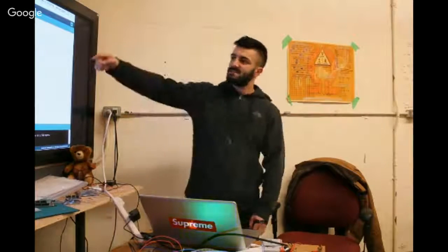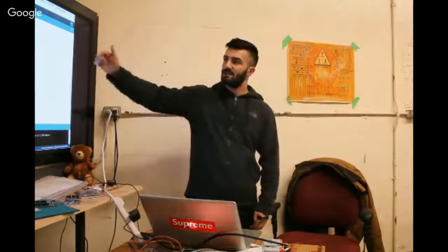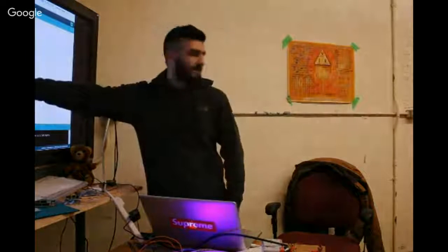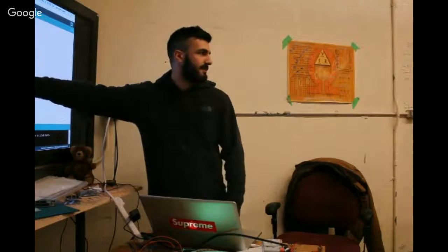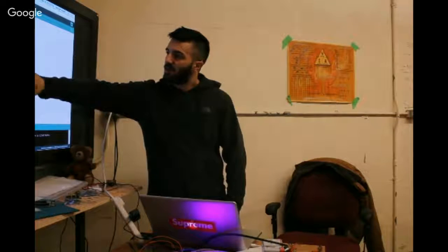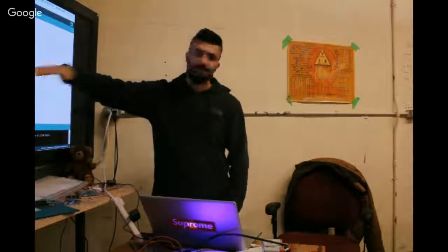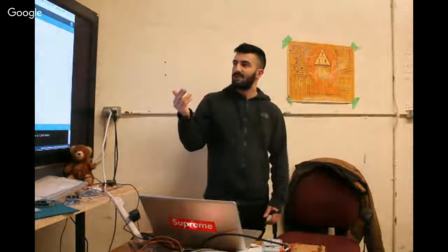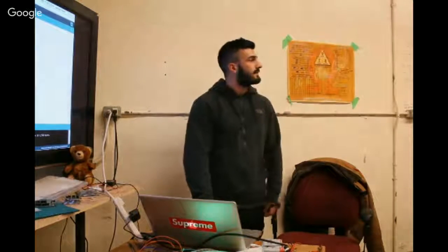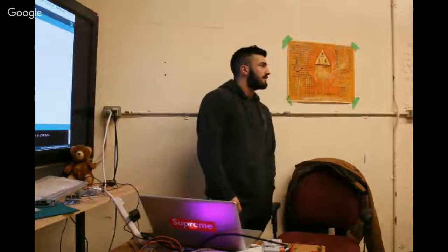Since the timers are starting up here, and then we detect motion, we want it to restart the fan set timer here. So basically, once we have motion, we tell the program to start timing 5 minutes, and it will count 5 minutes or whatever you decide the timer interval is. Another way of expressing this is that we'll run for 5 minutes after we got the last bit of motion. Right. Yeah, it's true.